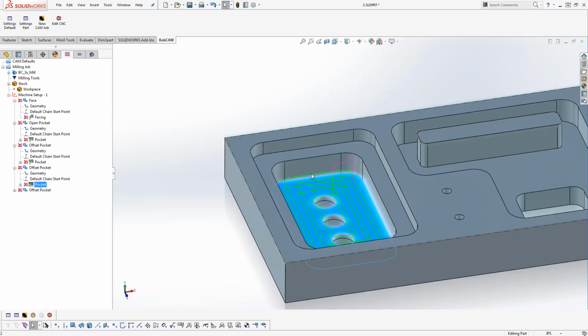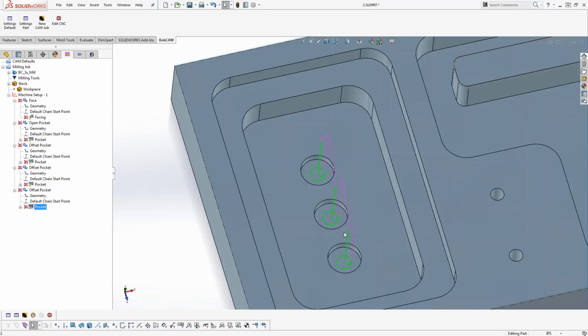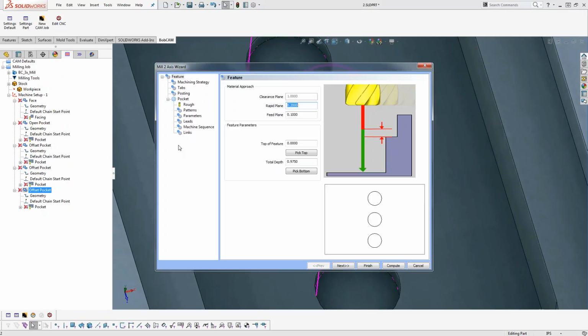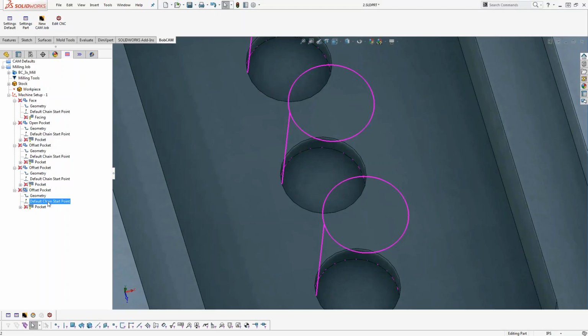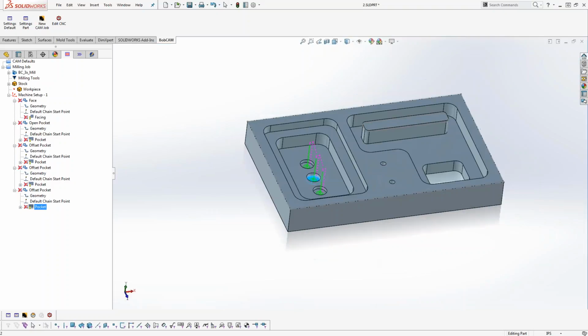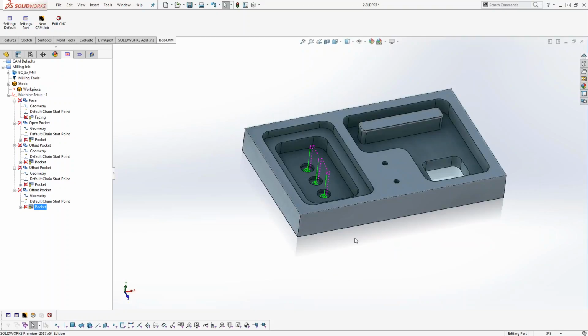And then on this last spiral here, I don't need to take it in multiple passes, but what I may want to do is adjust the step over so I get more than one pass in there, depending on the material. Here we could just drop down our step over and recompute, and then we're going to see an update. That is how this works. If you make a change to your toolpath, you do need to recompute your toolpath to update for that change.